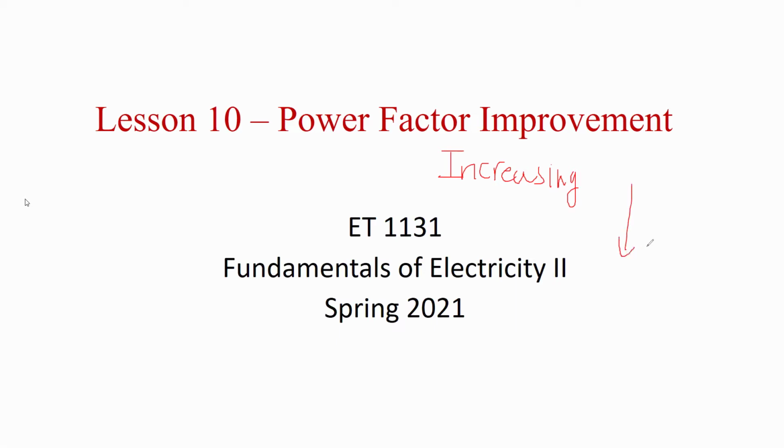By reducing Q. And when you reduce Q, you're going to reduce S. And because P over S is the power factor, when you reduce S, you increase the power factor. And now what is the reason why we improve the power factor? Because we're going to gain lots of things. The main thing is we're going to reduce the current in the system.